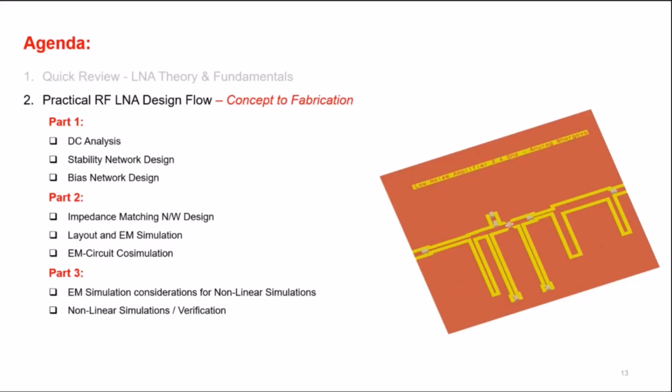I'm designing an LNA at 140 gigahertz. My circuit is single-ended. It again depends on what technology you are using, whether you are doing MMIC or RFIC. You need to be a little clever on that. And if you are doing RFIC, I would say doing a single-ended design is not a good approach. In silicon CMOS, you should look at doing a differential design. That will be helpful. But if you are doing MMIC using gallium arsenide, that should be okay. All right. Then somebody needs to look at what's going wrong in your circuit.